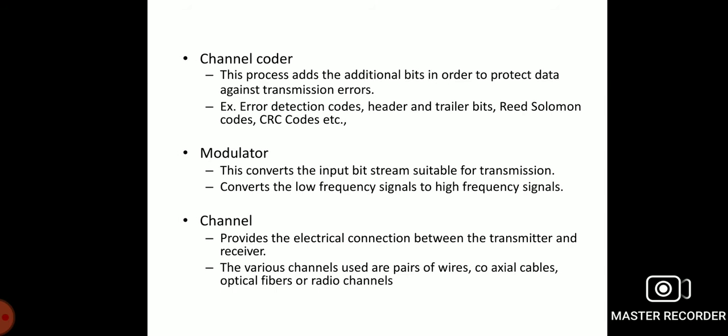The signaling procedures add control information for making and terminating the connections. The signaling information is protected using error correction coding. The multiplexer is used to combine the signaling and data information from many users. Multiplexing increases the data rate from 22.8 kilobits per second to 182.4 kilobits per second in GSM. The baseband modulator assigns the data bits to symbols. The baseband modulator makes the transmit symbols ready for transmission.